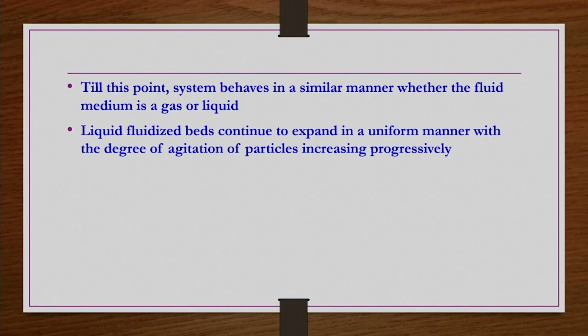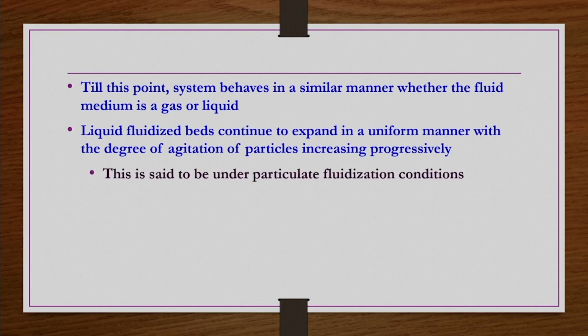Okay. Liquid fluidized beds continue to expand in a uniform manner with the degree of agitation of particles increasing progressively, and this is said to be under particulate fluidized conditions, where the average voidage at any cross section of the bed, if you take, is going to be approximately the same.